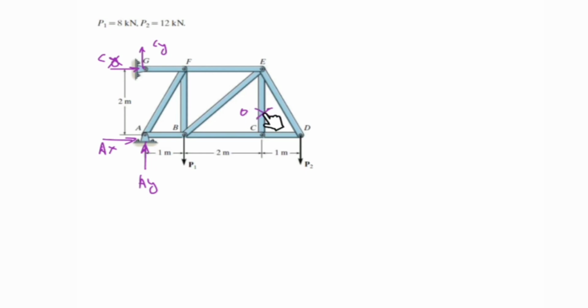If this is a zero force member, we can get rid of that. This is one link, this is one link, and if you solve this, you can get these two. You have 2 unknowns for here. This is done. You can do this and get here. You have these ones obtained from the previous sections. Find these two, and the same story here. 2 knowns and 2 unknowns. You can get these things, and that's done. For these cases, you can see we have 2 pins fixed to the ground, and you have some forces somewhere, and you can start with that point. Actually, you write down the equations for this one and start with that.